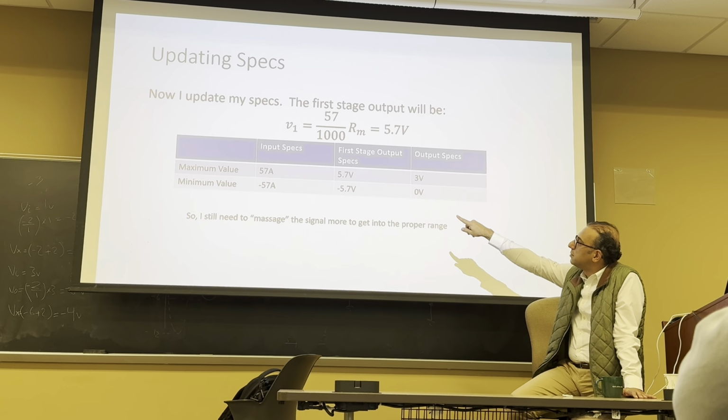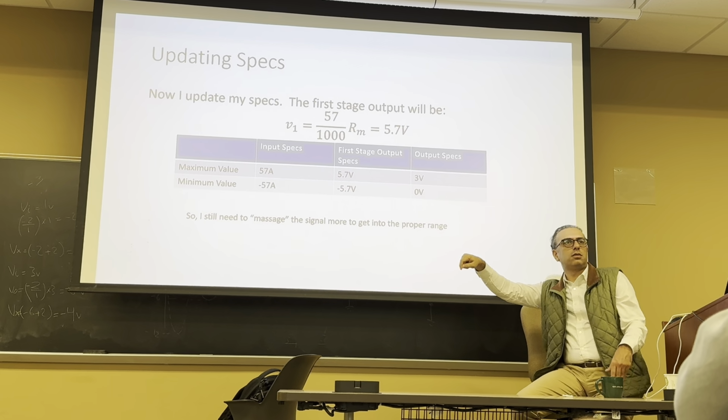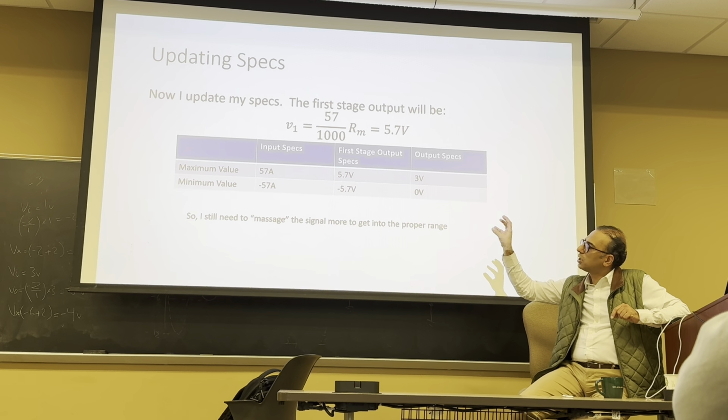Then it goes, do I have unipolar current measurements or bipolar? If I'm measuring the grid current, it's AC. So this particular sensor gives a bipolar output.